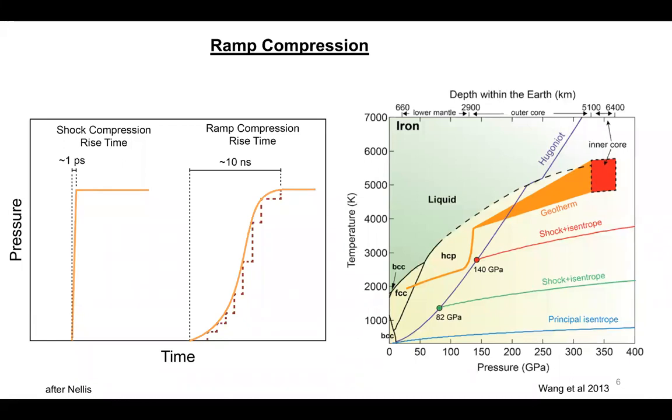Now, in the limit of an infinite number of shocks, the amplitude of each shock approaches zero, and this approaches a shockless isentropic compression curve. We can't achieve that in practice. There will be some dissipative processes such as plastic work heating, which results in some heating and some entropy increase. But there are some real advantages to this technique in comparison to standard shock loading.